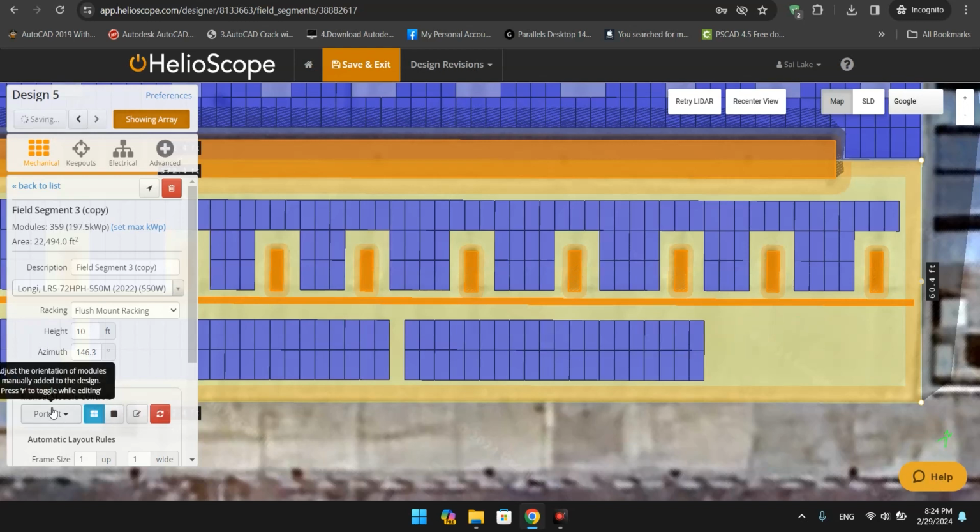I choose the portrait. If you want to put it in the landscape, use landscape, and you can also use a shortcut to switch it. If you press R on your keyboard, it will switch to the landscape, and type another R, it would switch back to the portrait.